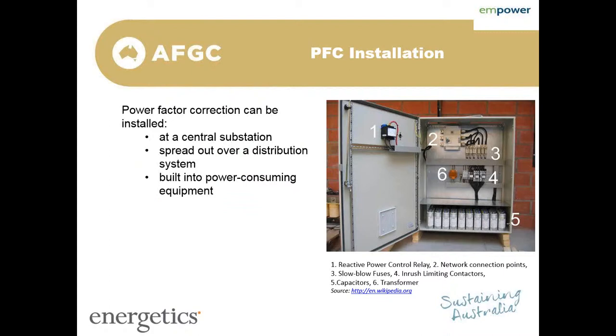With the installation, once we're happy that it's something we want to look into further, there are a number of companies out there that will install the units, and you can work out what's suitable for your site. Typically, you want to install the power factor correction as close to the large loads as you can, but often it's just done once at a central substation or the feeds of the site, because that's where you want to try to balance it out.